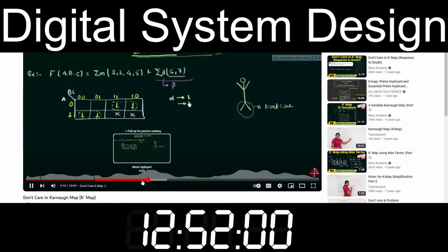We can take it as 1, we can take it as 0, whatever you want to, but we take it as 1 in case we have to reduce our K map by using the min terms, and we take it as 0 in case we have to reduce our function by using the max term. So keep this thing in your mind. This is when you are operating with min terms, and this is when you are operating with max terms. Because what we want out of the K map, we want the greatest possible group of the ones which are 2, 4, 8, 16 and so on, and we want it to be the largest.